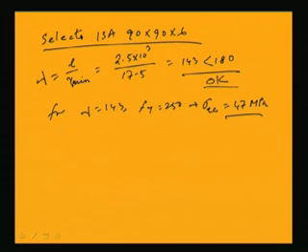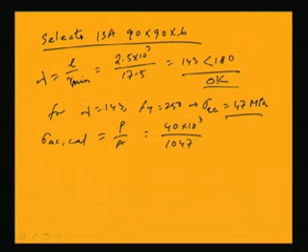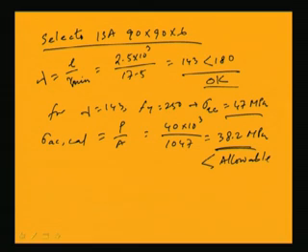Now, we can find out the developed compressive stress or calculated compressive stress, which will be P by A. P was given as 40 into 10 cube and area is given 1047. So, this will become 38.2 MPa. So, sigma AC calculated will become 38.2 MPa, right. Which is less than the allowable stress, that is 47 MPa.